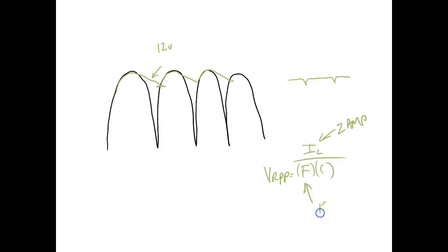Okay, it's going to be full wave. That's going to be 120 hertz. I know two things, right? You understand? So I know I can afford a ripple. So if we're going to regulate at 12, we don't want this thing to ever drop down below what? 12, right? You understand? So of course we would give ourselves some safety right there. So let's say we don't ever want it to drop below 12. We got 16 volts, right? Minus 12. That would allow us a V ripple peak to peak of 4 volts.